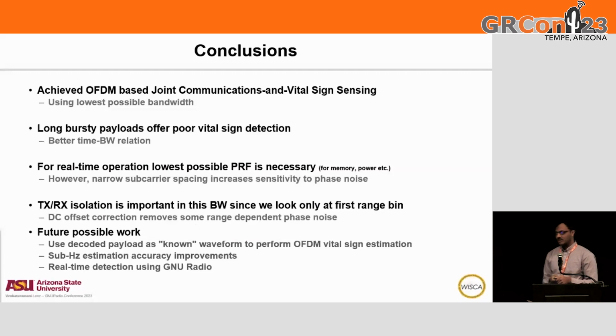In terms of the project we did, we operated the OFDM on the lowest bandwidth possible, and we could still see something. The reason we did that was for multiple reasons. One was that initially we tried to operate on these small NUCs, and we needed at least a long sequence so that we could get a good spectral estimate, and we couldn't process that much on the NUCs. So we tried to reduce the bandwidth, but that caused other issues. So eventually we processed it on MATLAB.